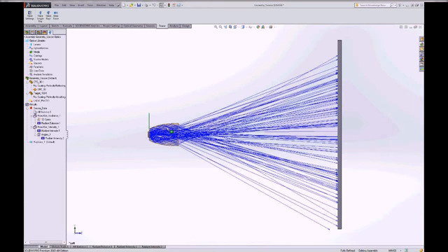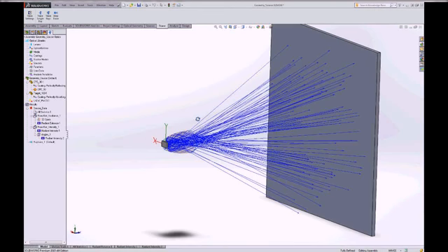Now, in this particular case, I defined this surface as a perfect reflector. There are no refracting components. If I had had refracting components, we could have generated Fresnel effects. I could have applied a surface texture to this to represent the scatter that we sometimes apply to surfaces. All of those could have been done, but in this simple model, we're not going to do that. So that's all there is to step 3. We've done the ray trace.